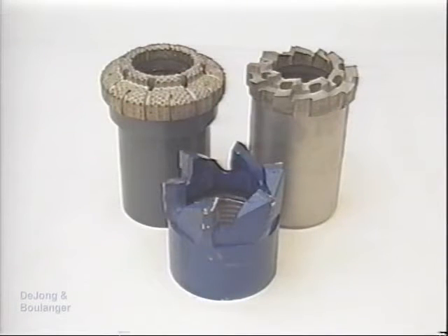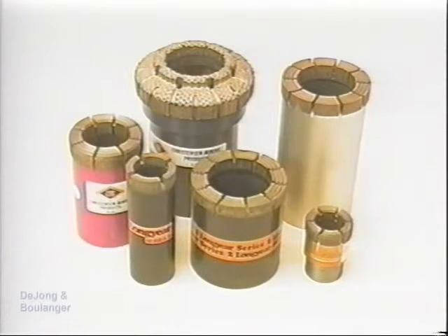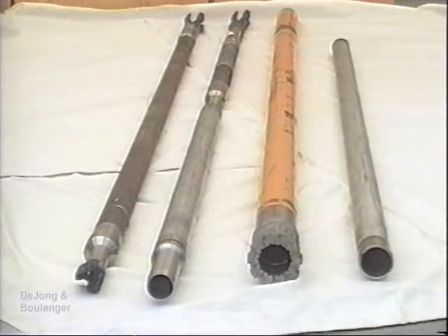Coring drill bits come in three basic types. Pictured from left to right are the diamond, carbide, and sawtooth. Diamond bits are the most versatile since they can produce high-quality cores in materials ranging from hard or very dense soil to hard rock. As shown, coring bits come in a variety of shapes and sizes, each of which is suited for a specific situation. Some systems, such as the Christensen 94 pictured here, can perform multiple tasks such as drilling, coring, and sampling.